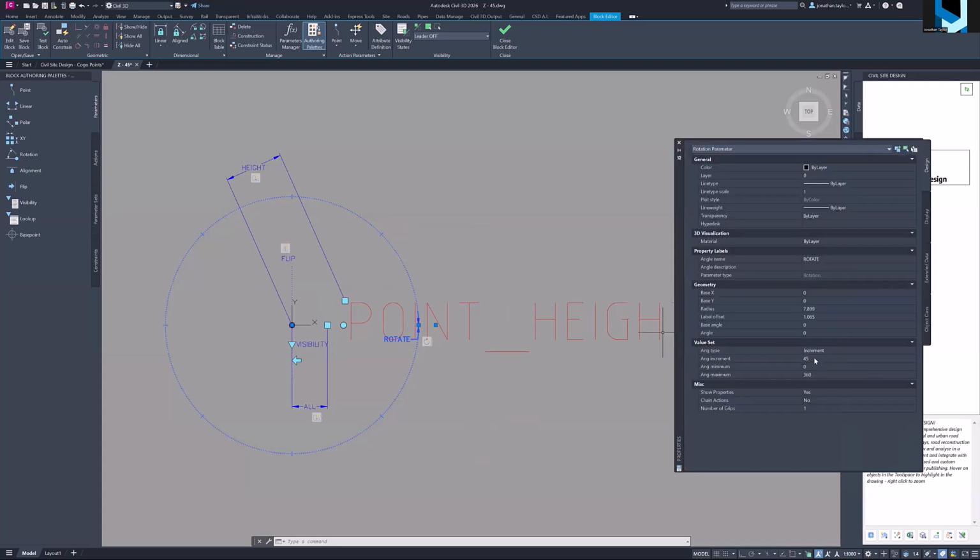Now, if you're in BricsCAD, you can open this. I would not recommend you do anything else with it, though. Unfortunately, if you begin to work in this and save it, you're going to override the parameters which you can use when this is inserted as a block in the drawing. So you're limited in what you can do. So all I've done here, rather than go adding lots of parameters, is tweak a parameter and add a 45-degree rotation on there.